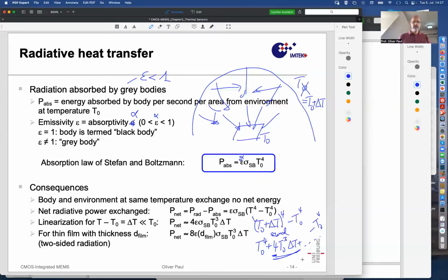So it's easy to calculate, and I just did a calculation before just to see how much watt I emit per square meter to my environment if I'm 1 degree hotter than the environment, and I calculated it's about 6 watt. So if I'm warmer by 1 degree than the environment, then we're exchanging 6 watt per square meter. And I'm about 2 square meters or 1.5 square meters large, so I'm losing about 10 watt per degree temperature difference.